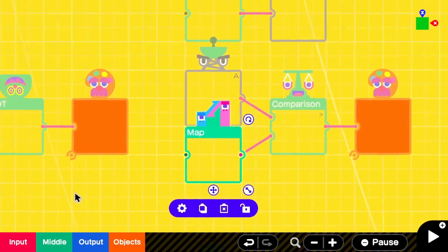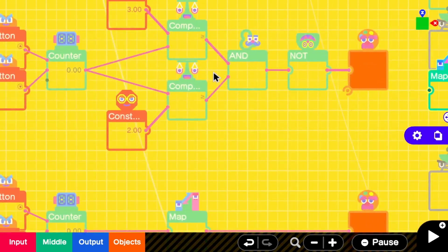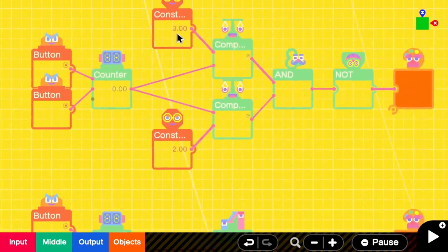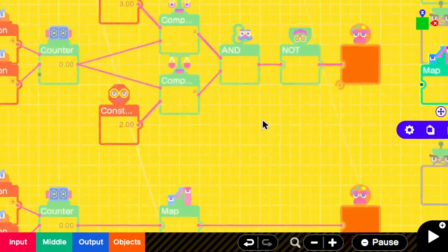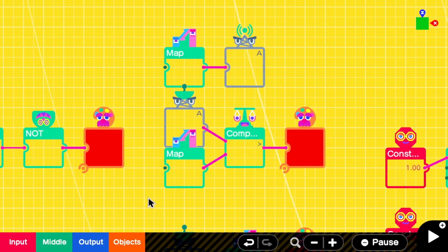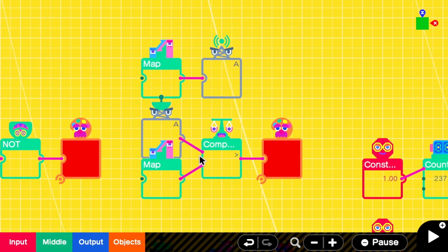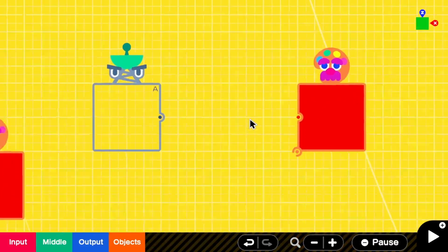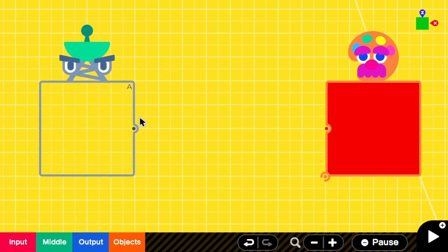In our typical solutions with comparisons, we can't use constants because constants only go to 1000, and the same goes for maps. However, we can use the same concept of 0.0001 to make a comparison that does this very efficiently. Remember, the number only needs to be greater than 0.0001 to activate logical inputs. Let's go down here. What if we divide the input by a very, very big number?